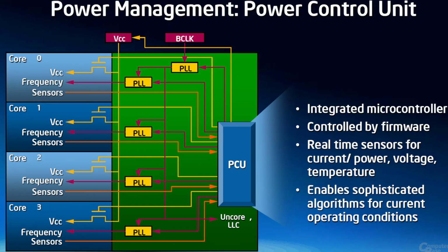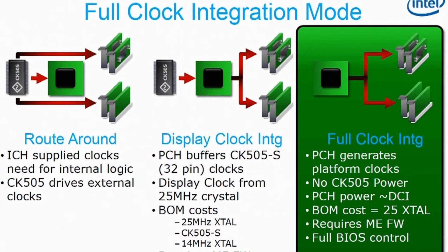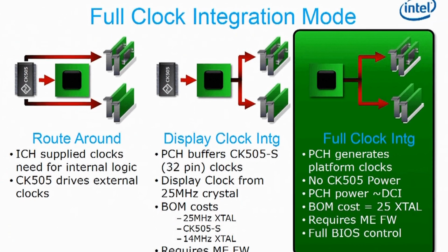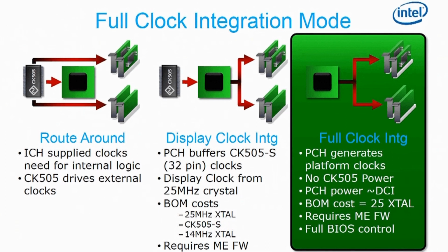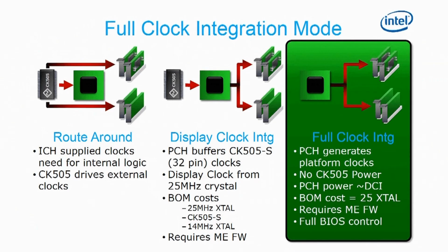The integrated power control unit was a key innovation of the Nehalem processor as it provided Intel control over the CPU's power management. Via its integrated microcontroller, Intel could set the power and performance rules of its processor, govern it, and if necessary, even change its behavior at a later stage through BIOS updates. With Sandy Bridge, Intel also added an integrated clock generator and essentially cut off any external control over the base clock frequency. Overclocking control was now almost entirely under Intel's control.